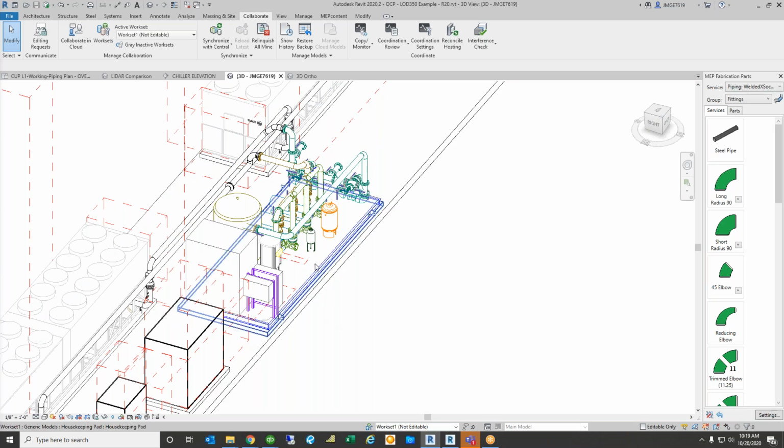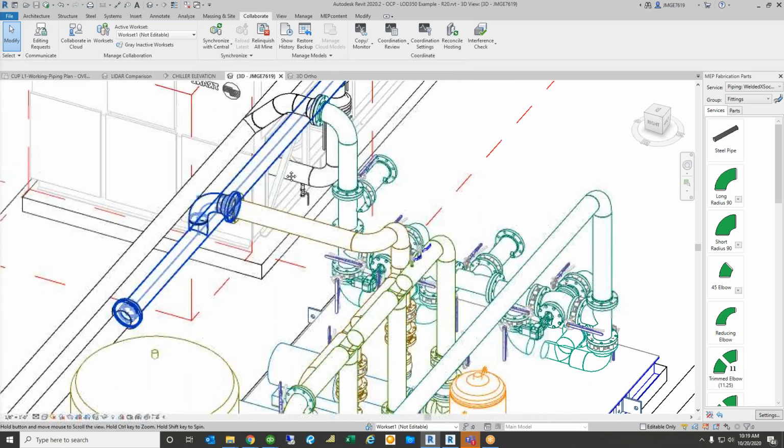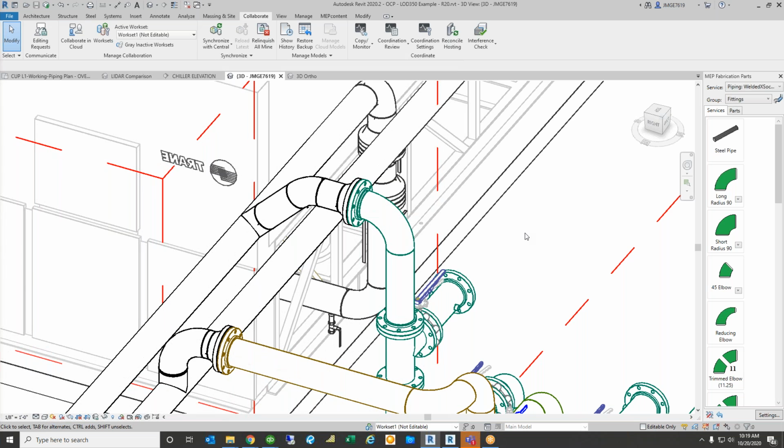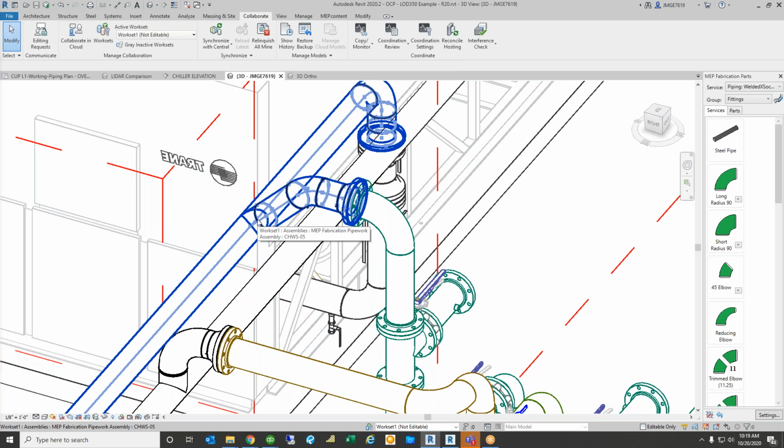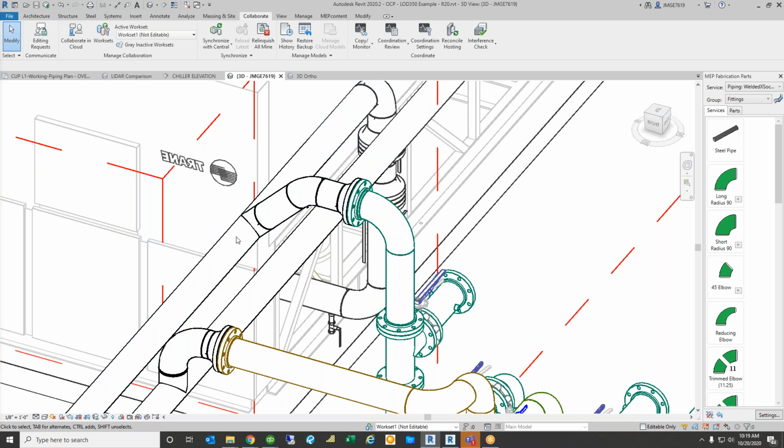And so what we do, and I've not yet done it on this particular set of drawings, which aren't quite yet due to the client, is we're actually going to make this a flanged connection right here, because we can get a bunch of stuff prefab, recognizing that this little section of pipe should probably be field measured and fabricated. So this is part of the discussion of things that we can do